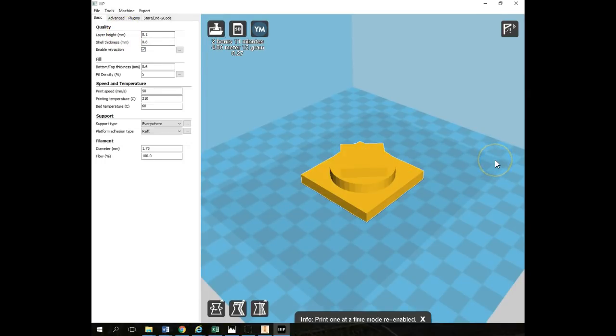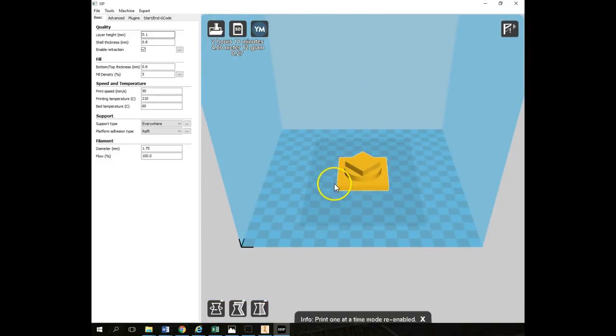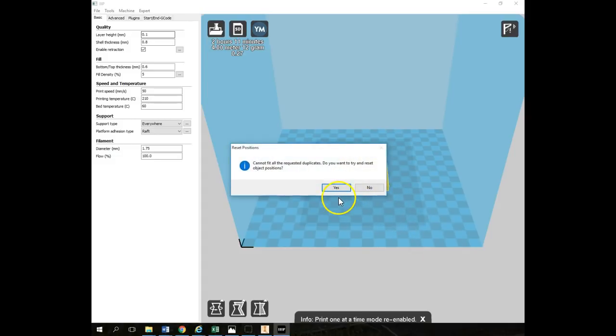Now, another thing we need to do, once it's sized on there correctly, once you can look at it and it looks, yes, 2" by 2"-ish, it looks like it's in an appropriate spot, you've got a couple of options. If this is exactly how you want it to be, cool, print it, export your G-code. Let's say you want multiple of these objects. I don't need one of these things. I need a total of 4, so I want 3 copies of this thing.